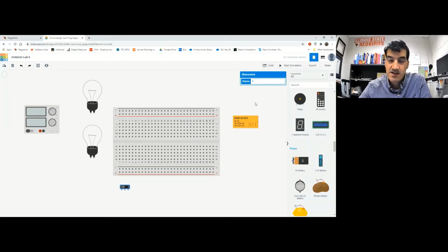Okay, so I'm going to go ahead and start by placing my relay. And these relays and these breadboards are designed to work together pretty nicely because it fits just right. If I put it right here, now I can connect to terminal 16 by putting a wire anywhere here. And I can connect to terminal 1 by connecting a wire anywhere here. And then terminal 13 is anywhere here. And then terminal 11 is anywhere in this column. Terminal 9 is anywhere in this column. And 8 in this column. And 6 in this column. So they're designed to fit nicely together.